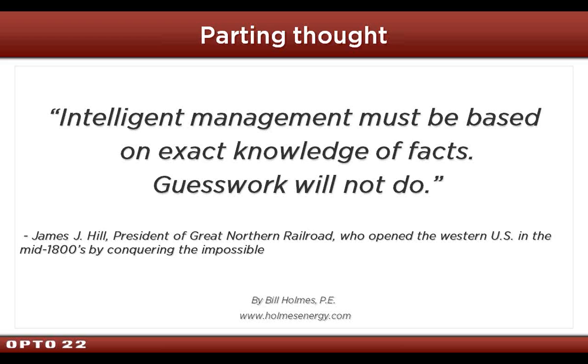Back in the old days when they were trying demand control and shedding loads, my approach was, if you understand what's happening within a facility through instrumentation, you don't need those emergency decisions, which I think often are poor ones or often interfere with production. We always took the approach that if you understood what creates that demand through monitoring, then you manage those loads so that you don't get into that peak demand situation.